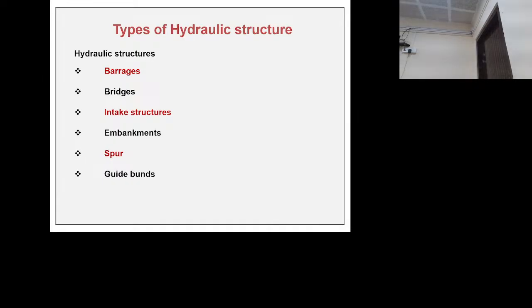First of all, we are doing mathematical model studies for Q of 2400. After that, we find out the flow water levels from 0 to 10 kilometers on the left bank and right bank. If anywhere we have seen any breaching or overflow at the embankment, we study it first in the existing condition. After that, if you find any overflow, then we have to measure the water level there,